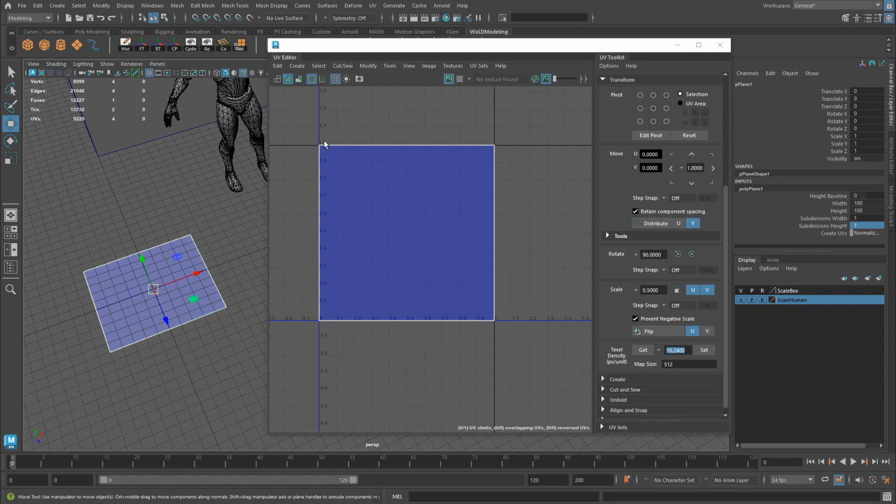And at the moment, the UVs occupy 0 to 1, the full space of the UV layout. So I want a 1K texture, 1024 by 1024, that would be able to fit into 1 meter of geometry and occupy its entire UV space. This is a good resolution to go with. So to get that texel density number, here's my plane. It's already occupying 0 to 1 space.